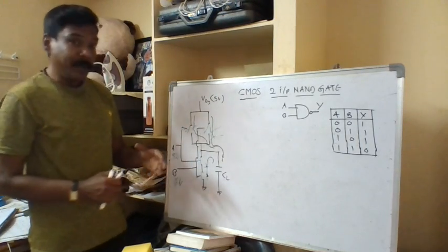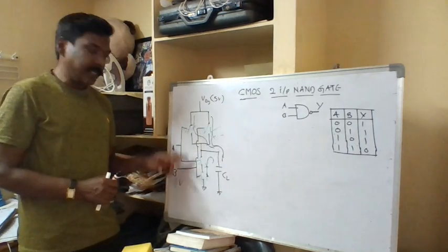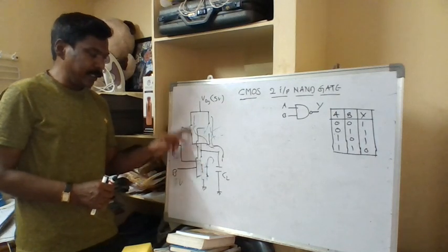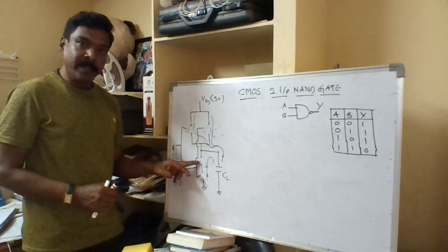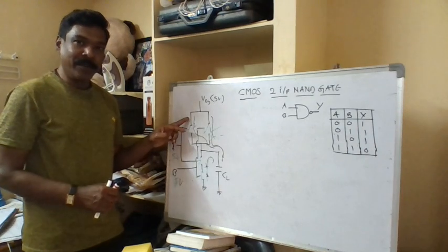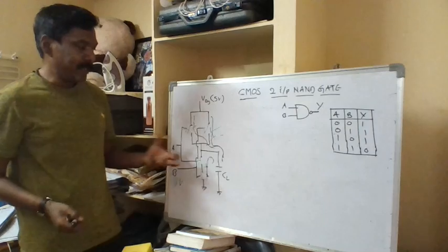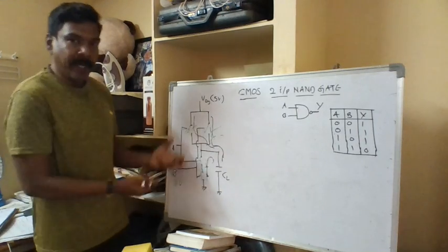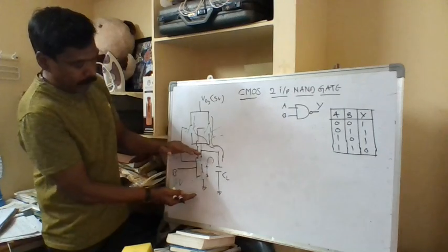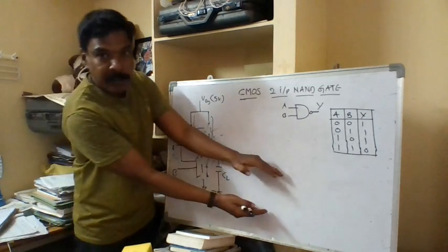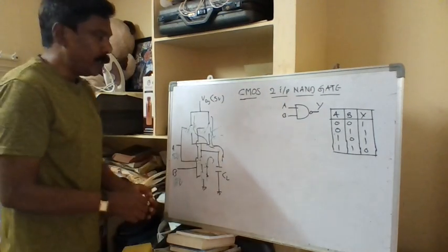So why PMOS and NMOS? When they are connected like this, both gates are given the same input. When input is 5 volt, the NMOS will be closed and the PMOS will be opened simultaneously. Because they behave like that, fulfilling this kind of arrangement, we replace the pull-up switches with PMOS transistors and the pull down switches with NMOS transistors. Okay, so let me draw that here.